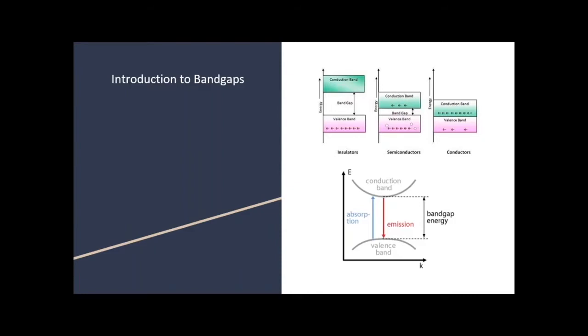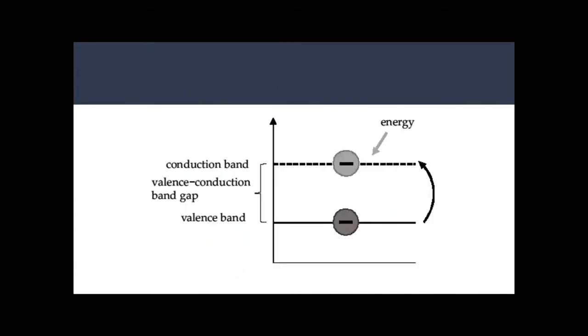where electrons can jump between the valence and conduction band with the help of outside energy, such as a light photon. And we're going to specifically be focusing on semiconductors due to the fact that they play a major role in generating electricity. So certain semiconductors, when exposed to light, its electrons absorb the extra energy, allowing the electrons to jump from the valence band to the conduction band, which generates an electric current.